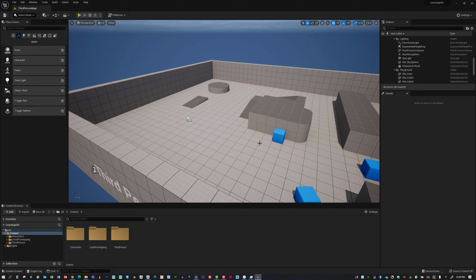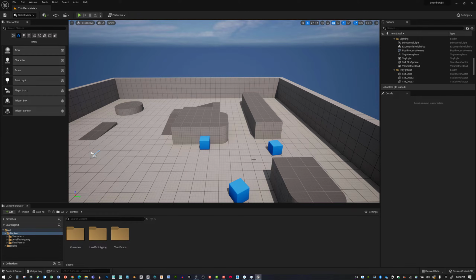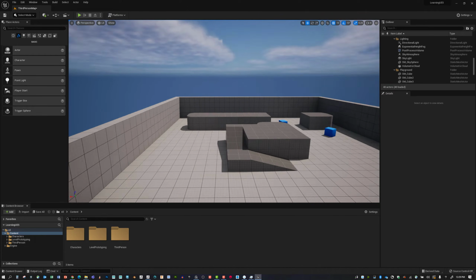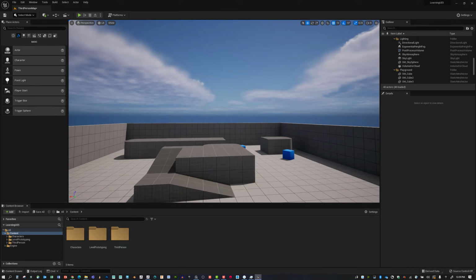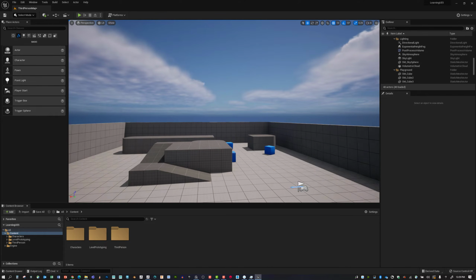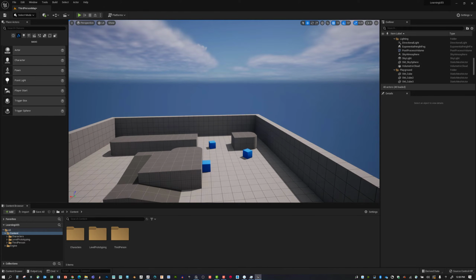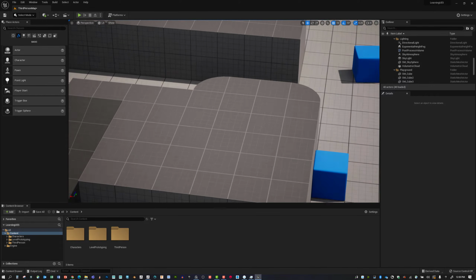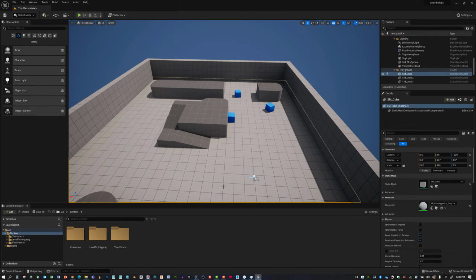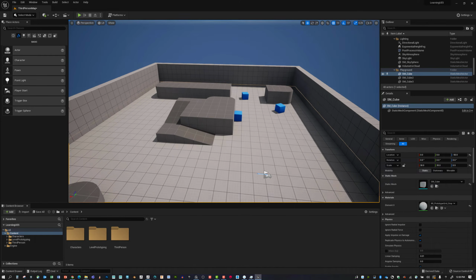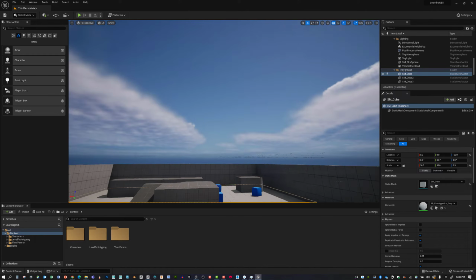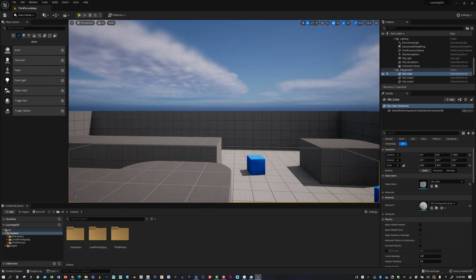The next thing that we'll take a look at is if you're used to first-person shooter games, you could hold down the right mouse button, and you could use W, A, S, and D to move around. If you do W, it's going to drive you forward. If you do S, it's going to go backwards. A is left, D is right. And I believe E will take you up in the air. C changes the focal length of your camera, and if you just let go of the right mouse, it goes back. So let's see, Q will actually take you down. E is up like this. So that's another way of getting around if you feel comfortable with that.